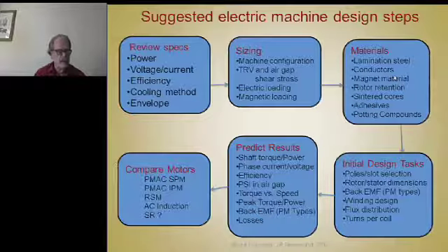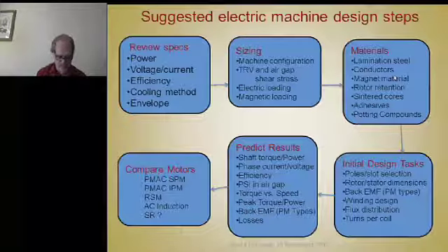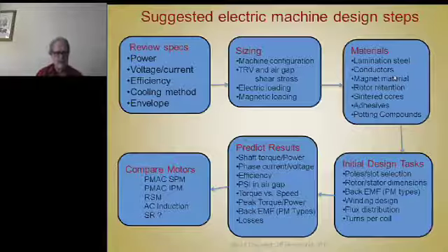The permanent magnet AC motors or brushless motors driven by sine drives can be surface mount or interior. Now this is very common: you've been told that you have to design a permanent magnet synchronous machine, but do a design comparison on an IPM or an SPM and tell me which one is best for us from a cost and performance point of view. And frequently you have to work with your inverter engineer on this as well. Other times people ask, can I replace our existing motor with an SR or induction motor or a reluctance synchronous machine, RSM?